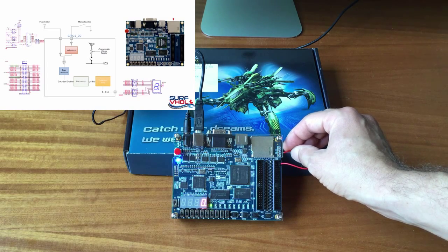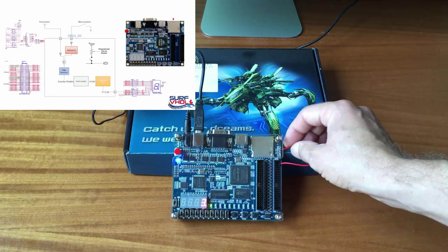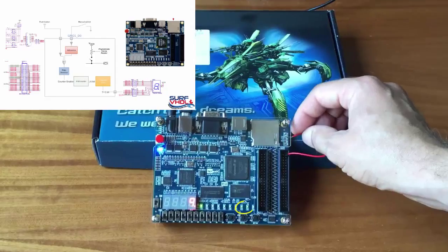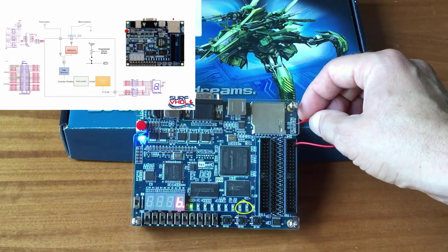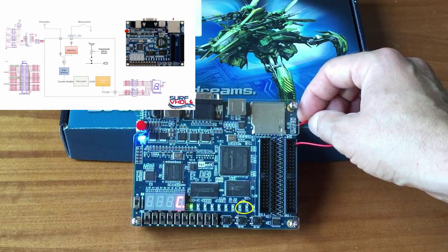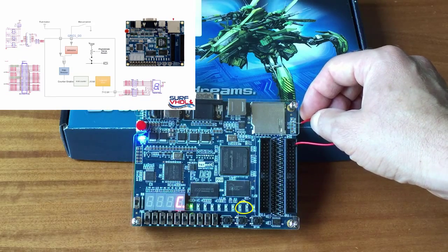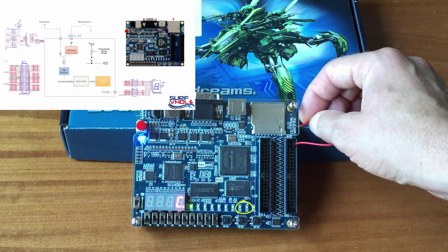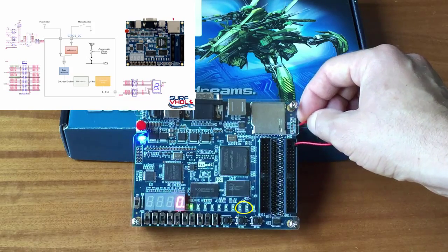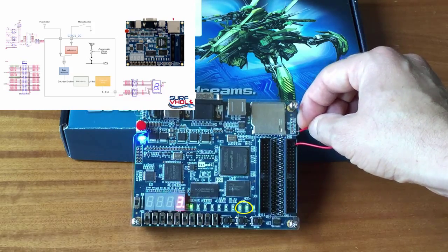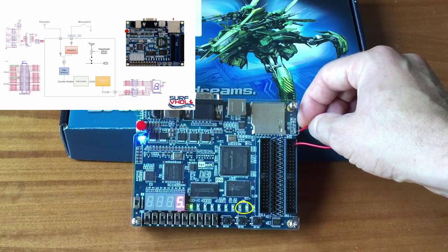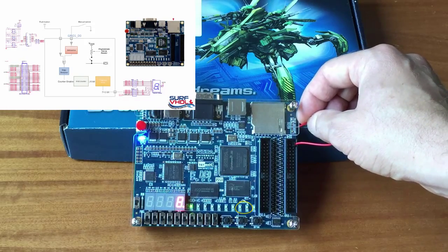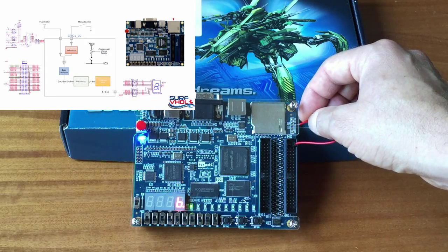As you can see, we have 2 blinking LEDs, one that blinks fast with all the input glitches detected, and the second one that blinks once. In fact, the counter counts +1 because we are filtering all the bouncing shorter than 40 milliseconds.